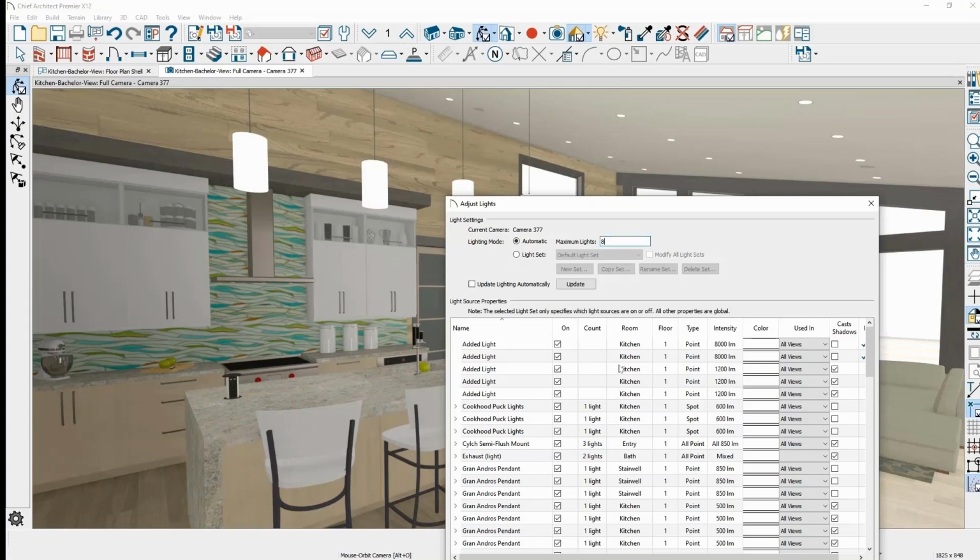Lights can be turned on down here. So you kind of come down and look at all of the lights, and there's a lot of lights in here. You can segment these and actually create a light set by group selecting these. That's kind of what I did. I created a light set by turning on different lights, and I created a kitchen and living room light set.